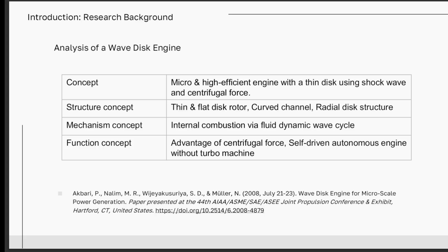It improves efficiency and simplifies the structure and processes by eliminating the piston or turbo machinery and reducing the number of energy conversion steps compared to conventional internal combustion engine or gas turbines. In addition, this structure can effectively leverage centrifugal force by enhancing fluid flow and supporting the self-driven mechanism.